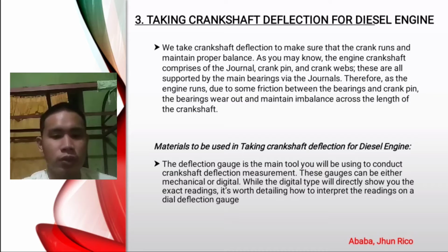So what are the tools or materials to be used in taking crankshaft deflection for diesel engine? We will use the deflection gauge. So what is a deflection gauge? The deflection gauge is the main tool you will be using to conduct crankshaft deflection measurement. These gauges can be either mechanical or digital.